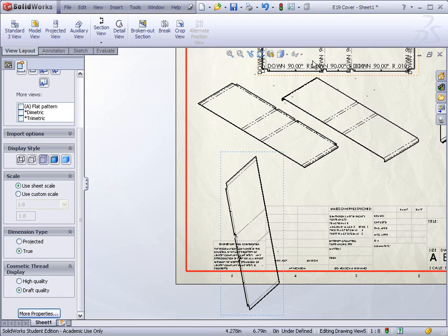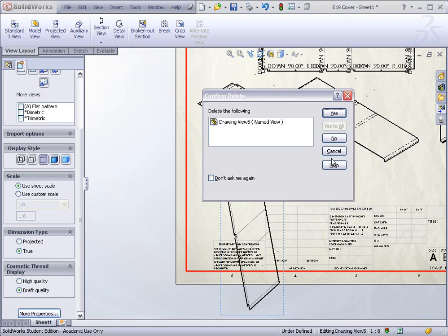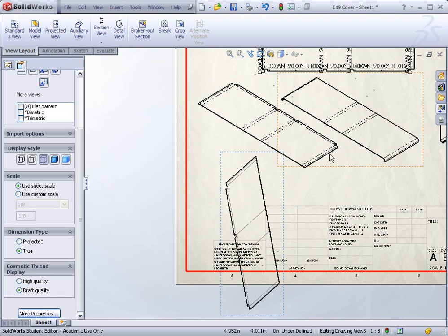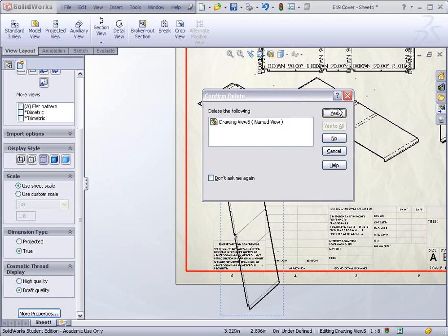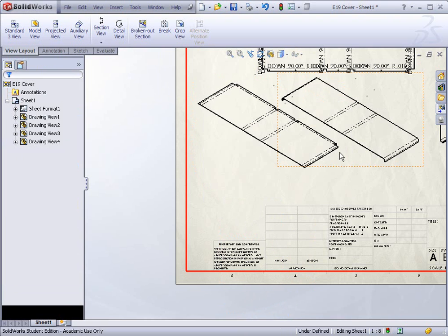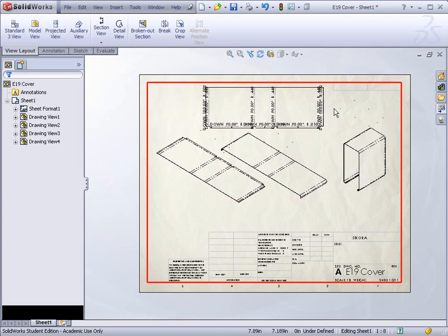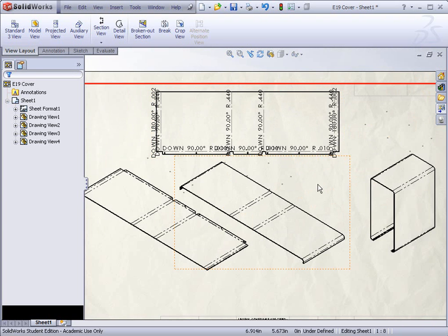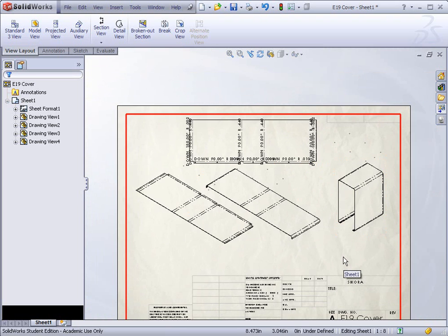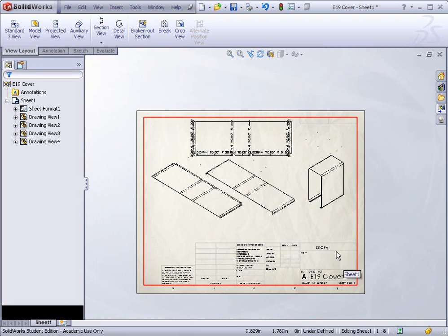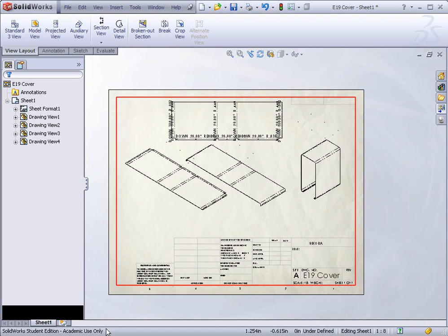Or actually, we might have wanted to make one more stage. Oh, stage, yeah, so this one's a little, if you wanted them all to look the same, unfortunately it's not working the way I was hoping. But anyway, we could have made one more flat stage, like a stage 3, that would have shown all those completely flattened out, versus using SolidWorks flat pattern, which generally wants to go flat like this and show you all the dimensions. Okay, that's about it for Save This Off as exercise 19, and that's it.